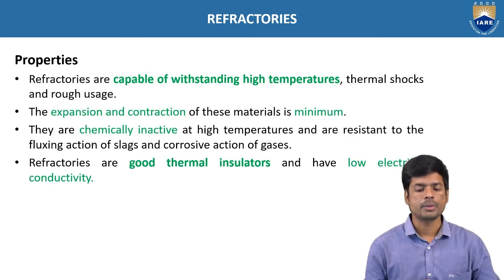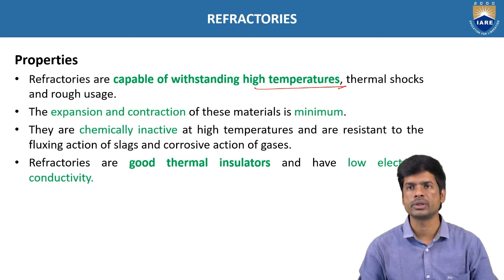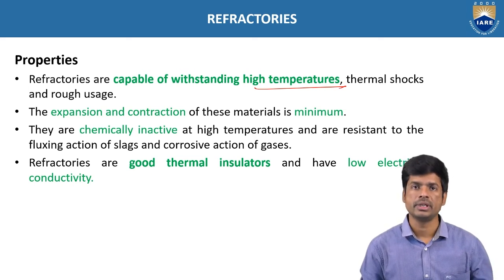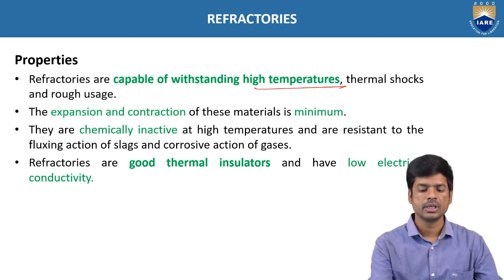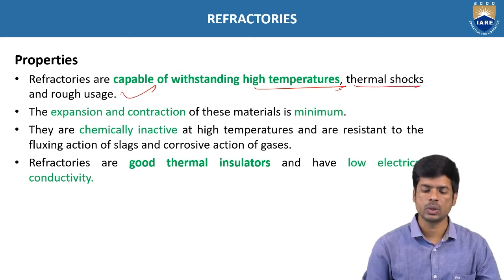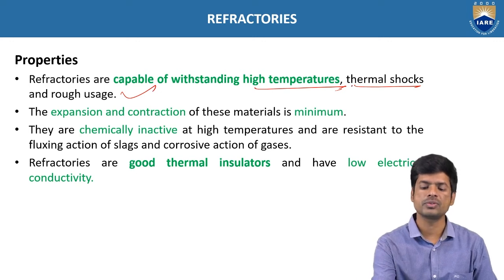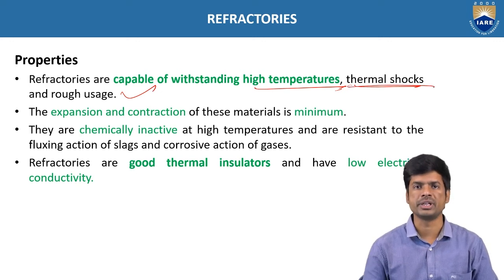Coming to the properties of refractories, the first property is that refractories are capable of withstanding high temperatures, as we already know. Compared to ceramics, these refractories bear more temperature. They withstand high temperatures, thermal shocks and rough usage. We can use them very roughly, and they can bear thermal shocks, so if you have any temperature variations, they can resist them safely, even when the temperatures are very high.